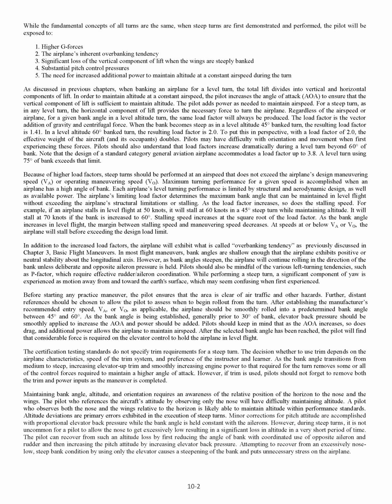Because of higher load factors, steep turns should be performed at an airspeed that does not exceed the airplane's design maneuvering speed, VA, or operating maneuvering speed, VO. Maximum turning performance for a given speed is accomplished when an airplane has a high angle of bank. Each airplane's level turning performance is limited by structural and aerodynamic design, as well as available power. The airplane's limiting load factor determines the maximum bank angle that can be maintained in level flight without exceeding the airplane's structural limitations or stalling.